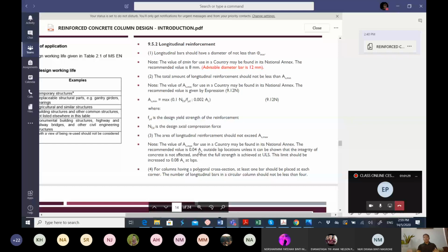So it is better for you to have more, so that at the long dimension, for example on the x-axis, which is at H, normally the size is much bigger than your B, maybe in between you need another reinforcement. So it depends on how you arrange your own reinforcement and how you decide the number of your reinforcement. For the rectangular, normally it is an odd number. The minimum number is 5. It cannot be 3, it's quite weird if we have 3. The spacing should be equal.